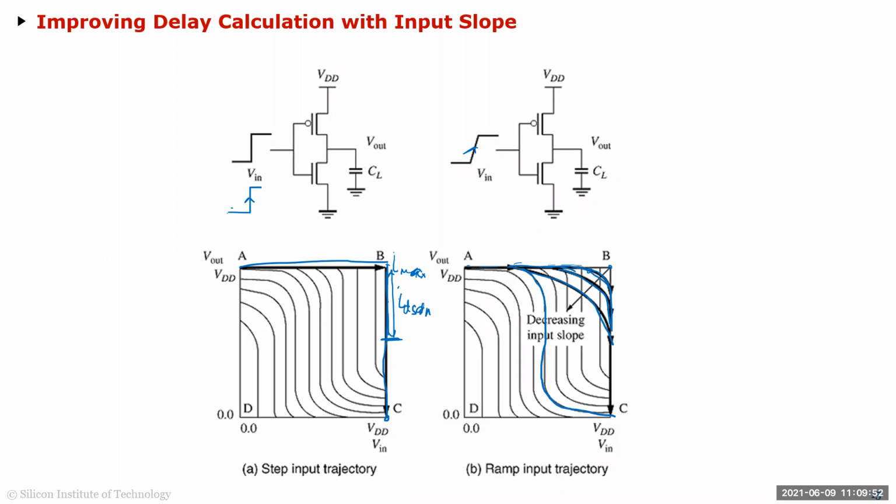For example, the delay of the switches comes from the resistance of the switches. I showed you what the switch resistance is dependent on. And we said, if you're doing 50%, then it is dependent on just the ID sat current. Then we looked at the caps. The fan out cap, which is the gate cap of all the gates, we calculated all the different types of caps, which you have already covered, and how to sum them up.